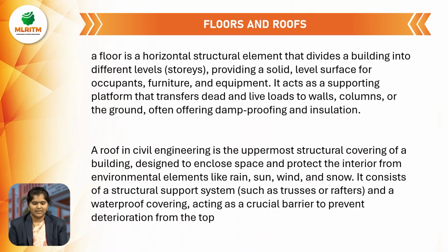Floors and roofs. A floor is a horizontal structural element that divides a building into different levels, providing a solid level surface for occupants, furniture, and equipment. It acts as a supporting platform that transfers dead loads and live loads to the walls and columns, often offering damp proofing and insulation.